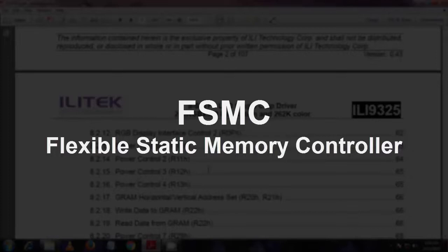So this same principle we will use here, except we are using the LCD. In this LCD we actually have a static RAM. That means a memory for storing data. Now this LCD module actually works on that data. So whatever data we write in this memory inside this LCD module, our LCD module will behave according to the data. That means we can write data like a complete sentence and the LCD will display that data on the screen.